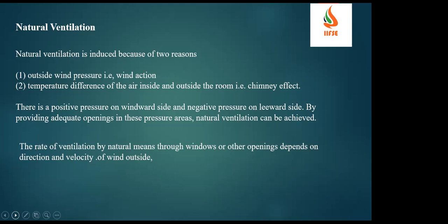If the temperature is very high in your area, the fresh air comes in, because the air in your workplace is already heated up and always tends to escape from that location, so a vacuum is created due to that chimney effect, and fresh air always has a tendency to come in.